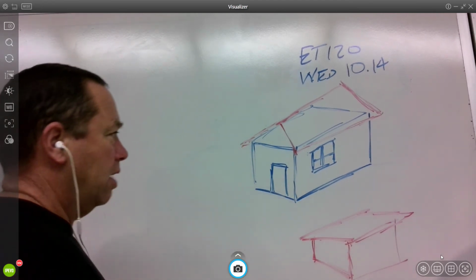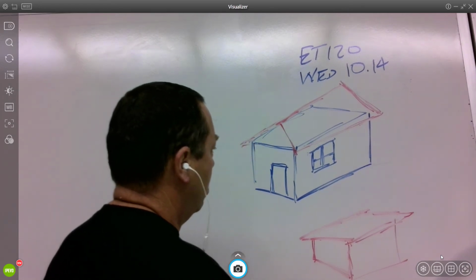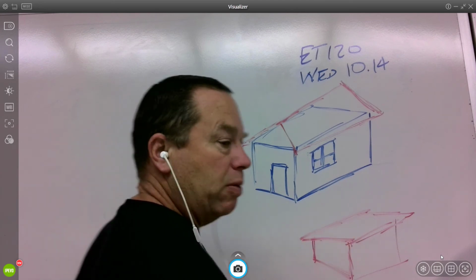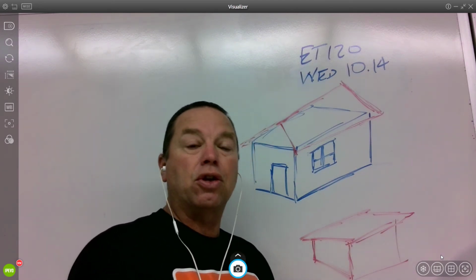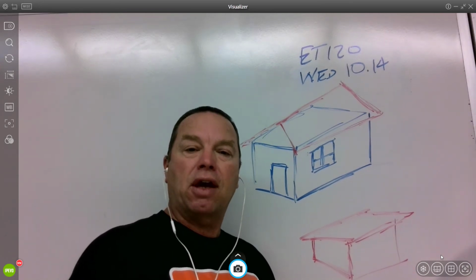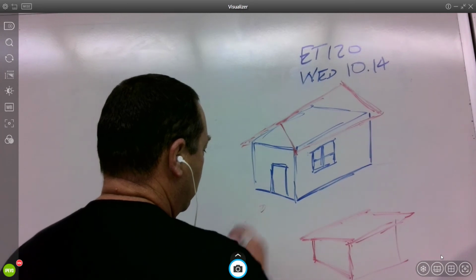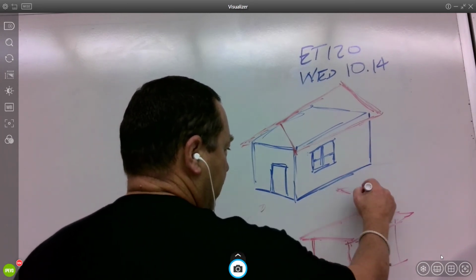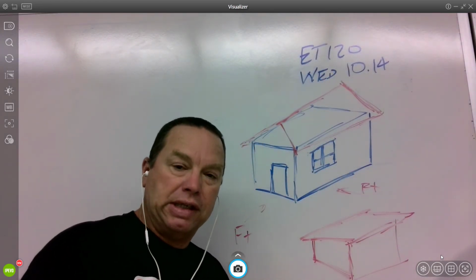Okay. So it's got to have, you know, a door. It can have more than one window if you want. Doesn't need anything else. We're just going to keep it like that. But then once you get it designed three-dimensionally, you're going to create a front, top, and side view. So you can choose what the front is. You can call this the front, this the right side, and then a top view, which is going to be what's called a roof detail.